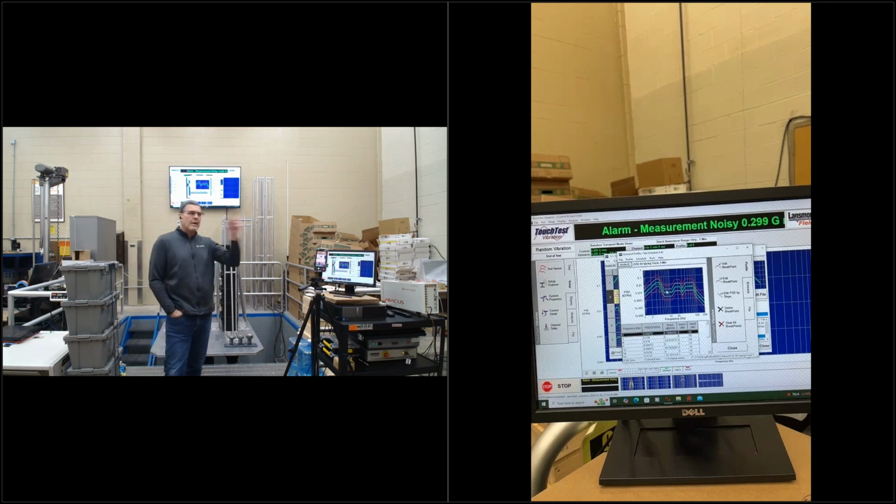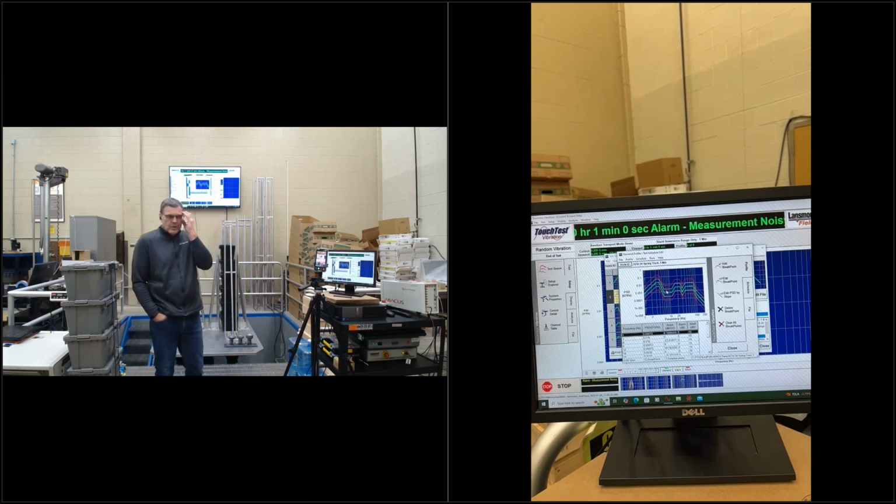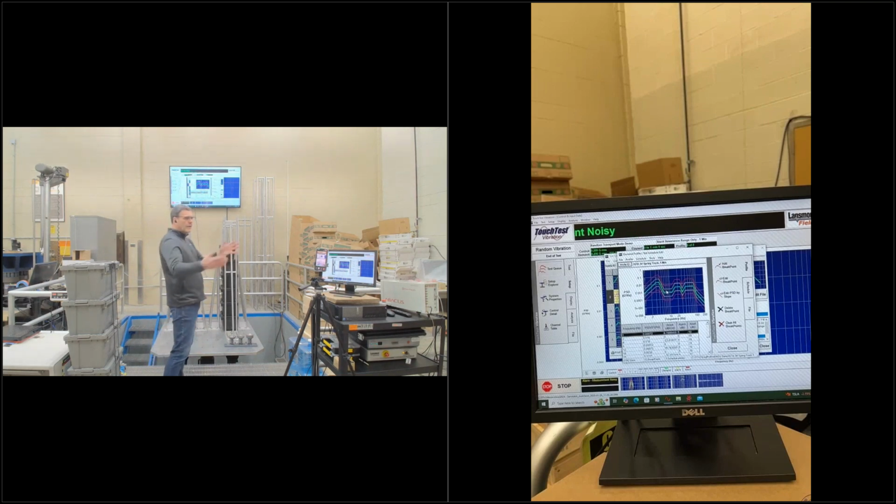And of course, when you develop these tests, what's most important in all of this is that you have some, hopefully some way to do damage correlation. If it's just a pass/fail test, so be it. But you've got to hopefully be able to close the loop, so that the results I see at the end of all this testing, not just vibration, but drop, vibration, compression testing, correlate with what I see in the real world.